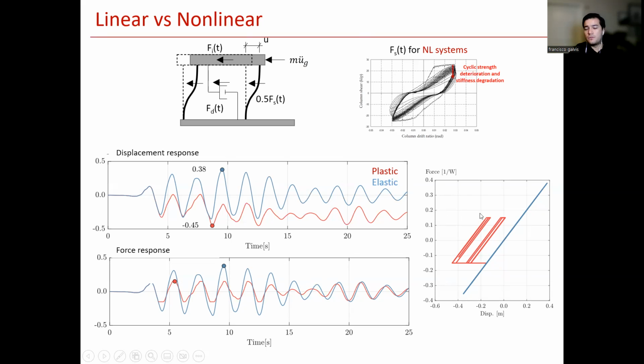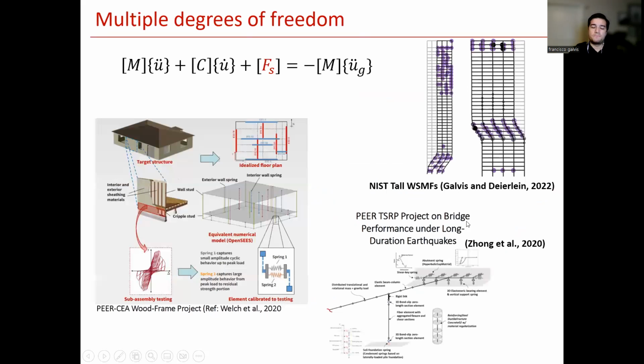Now, here on the right, you can see the comparisons, overlaying the hysteresis loops, displacement by force plots, with the elastic structure, of course, being a line. Displacement is always proportional to the force by the stiffness, but with the plastic structure, it's like that until it exceeds the elastic limit, and that way it will just go through this plateau here. And if it tries to go back, it goes back now with a permanent displacement.